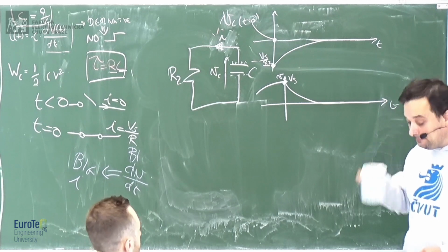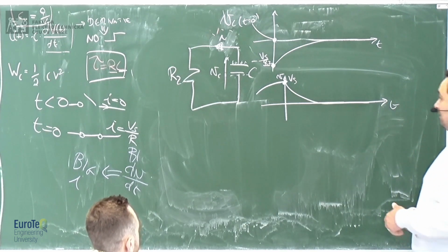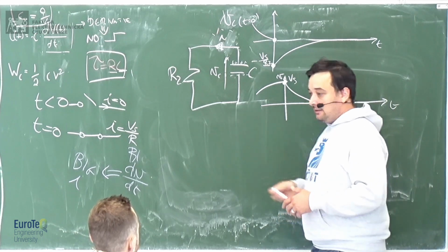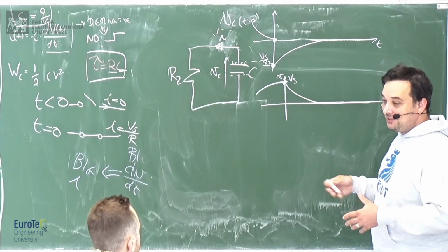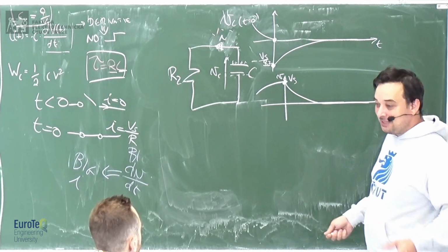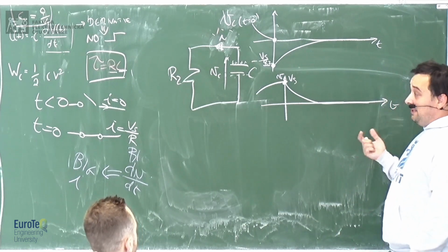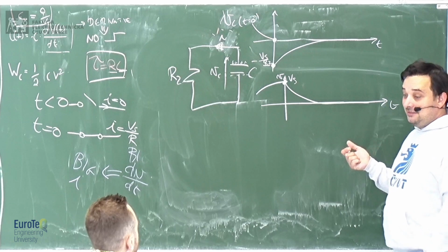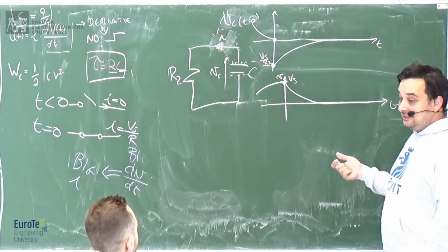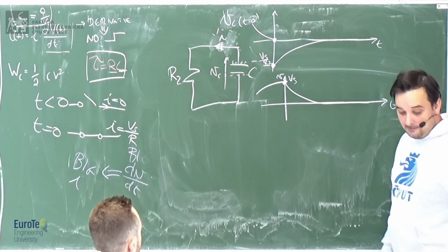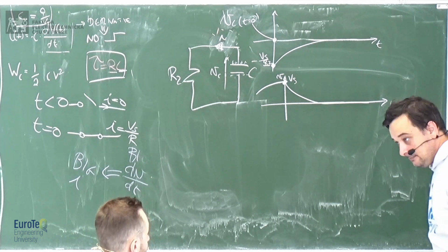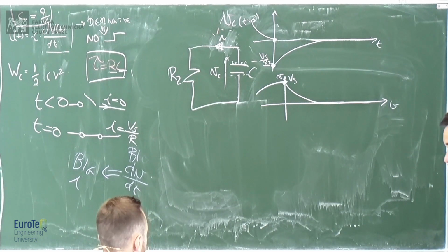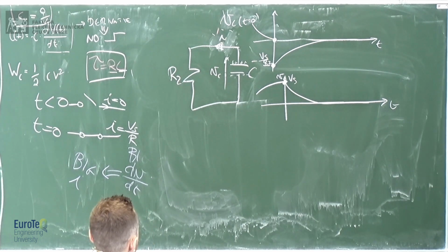So when you turn it off, when these things become more and more important, they try always to give you ways to do it safely and not just search around some random capacitors. Because very often people tend to forget these things. Especially if you have an LCR meter and the capacitor is charged with a greater voltage than what the device can take. So don't forget that. Always discharge a cap.